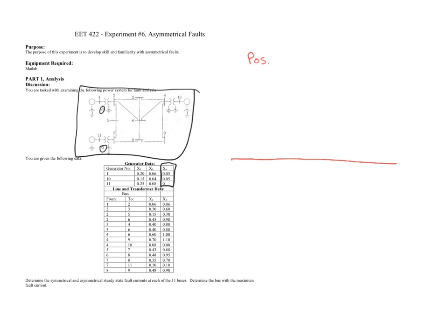Since a positive sequence diagram is a balanced diagram, we have no concerns about how transformers or generators are connected. We'll just have the currents and the voltages being passed through regardless of any connection. So the first one we're going to do, show our generator supply. We'll just call this G1 since it's connected to bus 1. It'll have its internal impedance here.